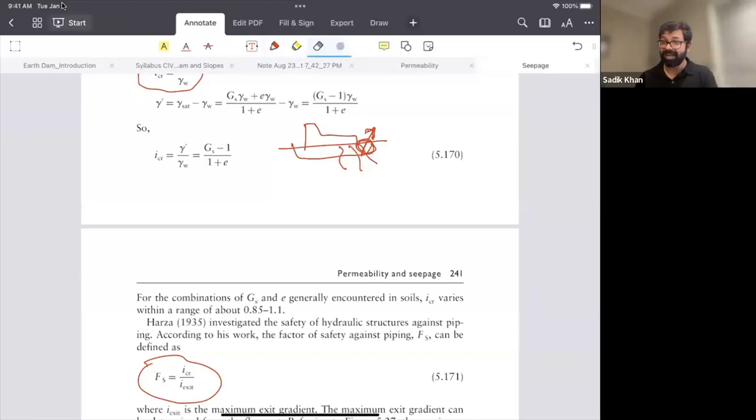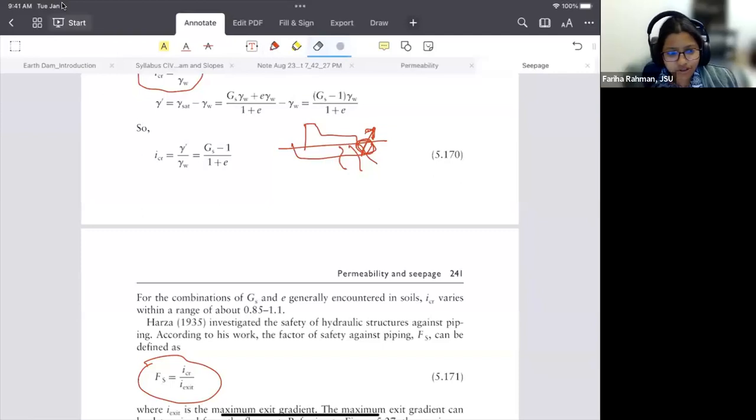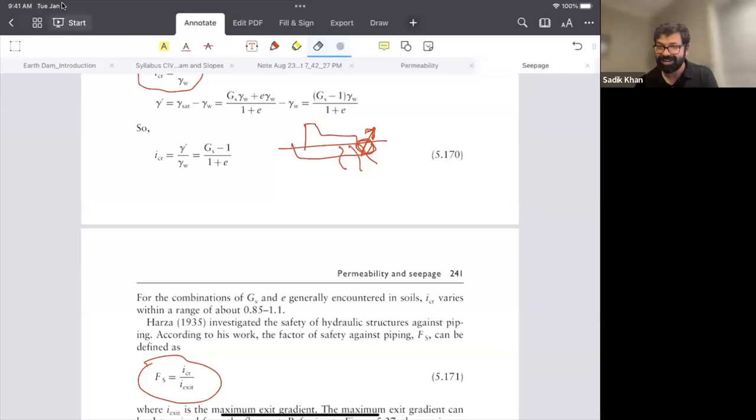How does water keep the pressure? Well, the pressure depends on the height of the water, because it is always a pressure flow, right? So to keep the pressure, what do you need? You need the height. You need the confinement. If you don't have the confinement, you don't have any pressure. Water holds the pressure when it has confinement. If you release the confinement, you release the pressure. So we open the spillway.